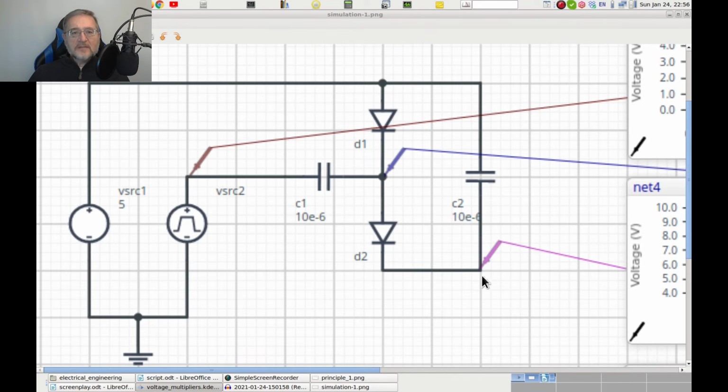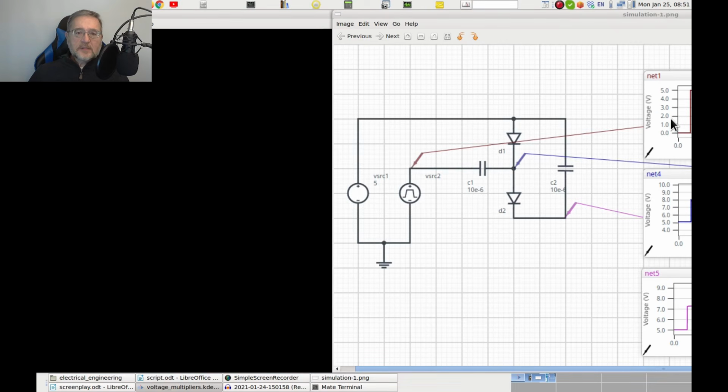The signal that drives the whole circuit is of course the square wave. Let's see what happens each time its voltage changes. When we power up the circuit, the square wave value is 0 volts, which basically connects C1 to ground. In this condition, diode D1 is forward biased, with a positive on the anode and ground on the cathode through C1, and therefore can conduct current. We say that the diode is on.